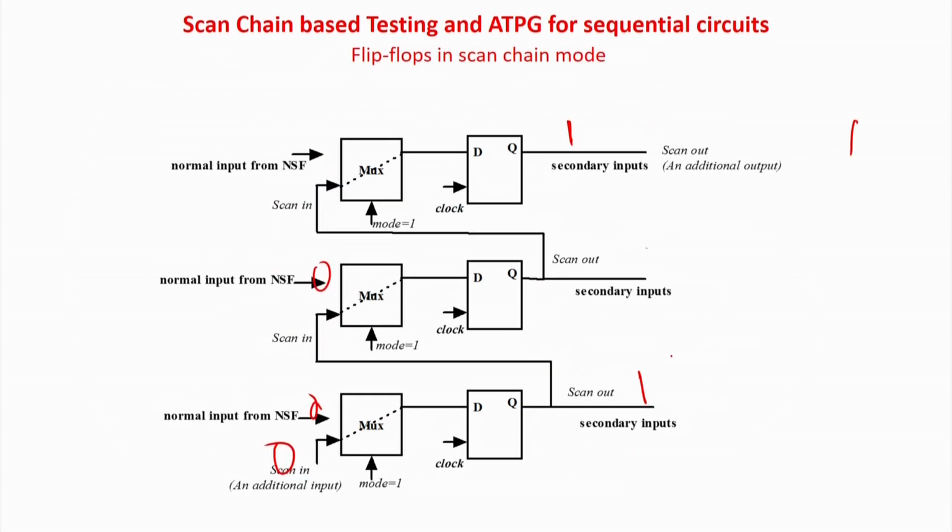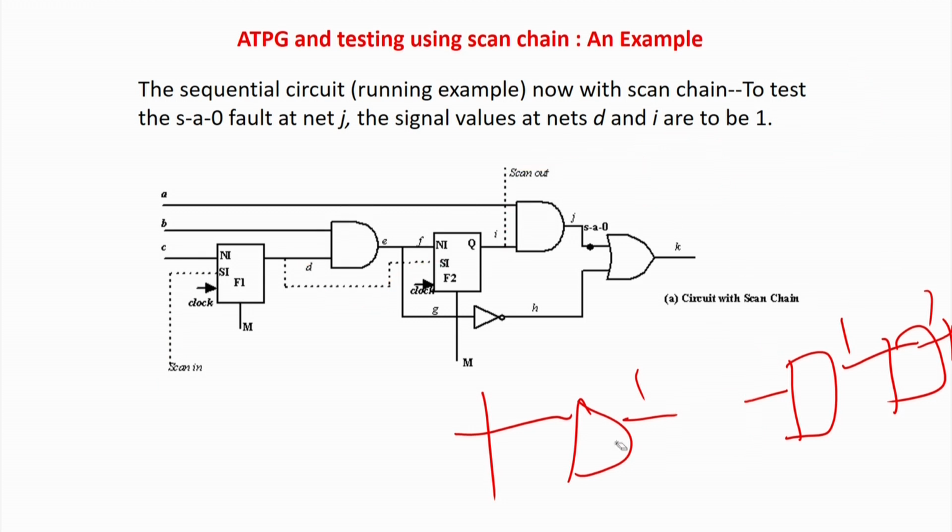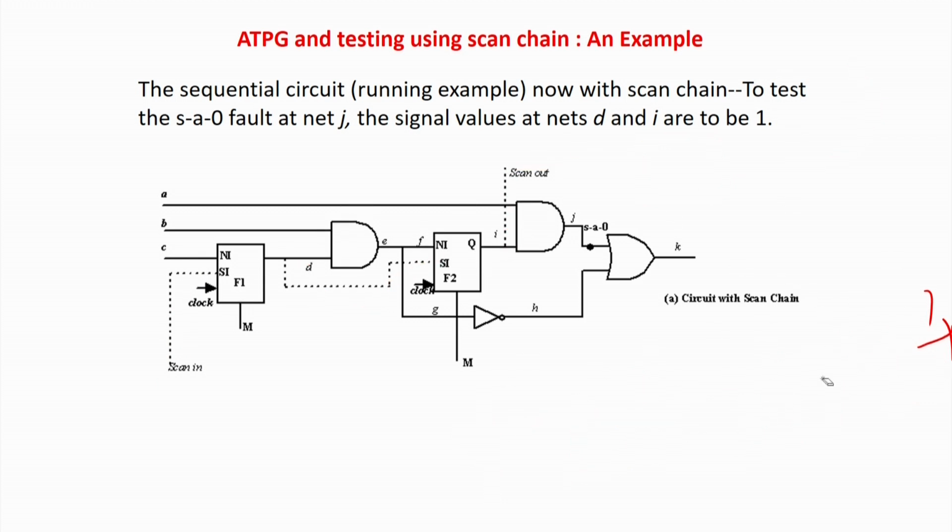So, in most VLSI circuits, if you look at the flip flops, you will be surprised that all are scan flops. Because scan chain is a de facto standard that has come into the picture for all circuits. Nobody actually uses a normal flip flop. If you have some experience in designing CAD circuits, you will be surprised that all the flip flops are scan flops, because nobody bothers much about area, but the only way to get access to the circuits inside is a scan chain. Even when going to NOC and SOC, to get to the internals of the circuit you should have a scan chain.